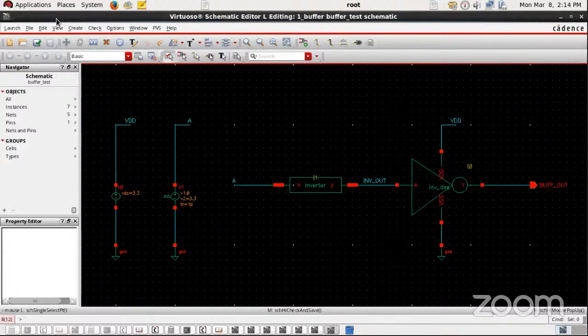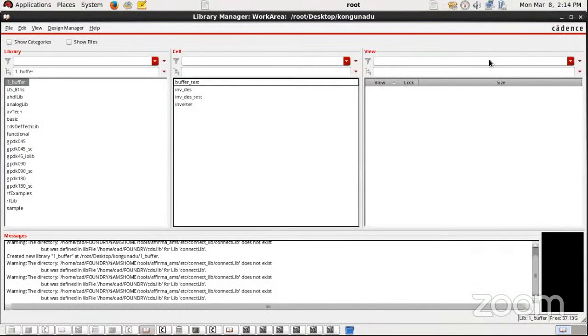We cannot use the AMS simulation engine directly because we need to specify what the target library and the target design flow are. That is the reason why we cannot directly make use of the AMS design flow. So I'll close this and create a config view.